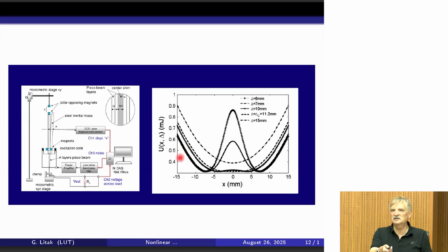So the larger deformation is related with larger amplitude, because otherwise there is some decay of the voltage. So if you bend the beam, but it is connected with the electrical circuit, then the charge would flow around the circuit just to balance the polarization of a piezoelectric, and finally it would stop.